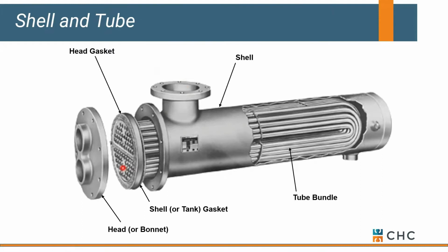They're typically 3/4 copper. Normally you come in down low with your coldest fluid, you circulate it through your tubes, and it leaves warm nearest the source. So that's all we're doing with this guy. It's a shell and tube heat exchanger.